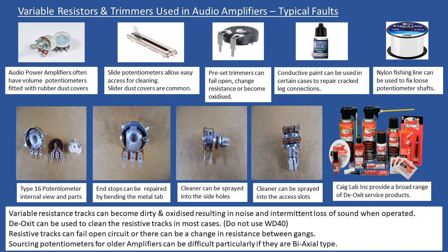But remember that all these potentiometers have a tolerance, right? So I'm not going to measure and expect to see 20.0 k ohms. It may be 19.8 k ohms. But as long as the two gangs are nominally correct, then that would be fine. But you may well measure one of the gangs and maybe you don't get any resistance values between the wiper and maybe one of the other connections. So that would tell you that it was open circuit at that point.